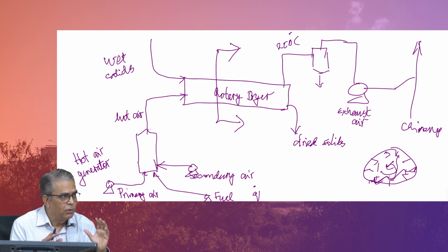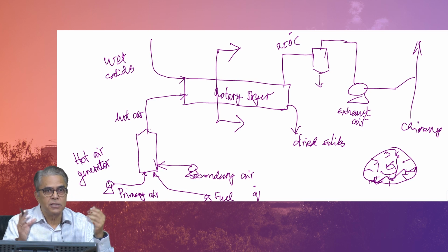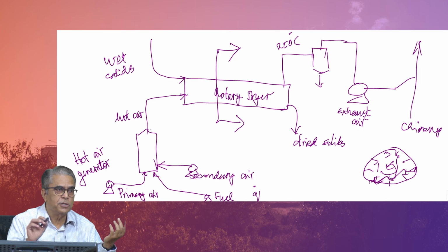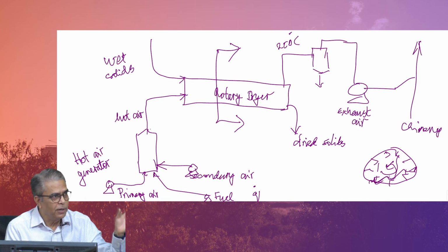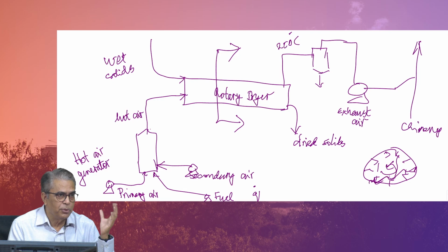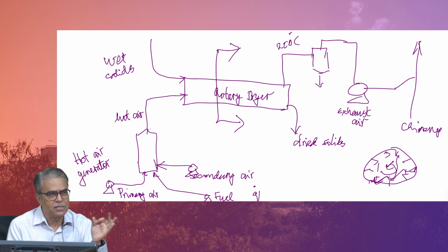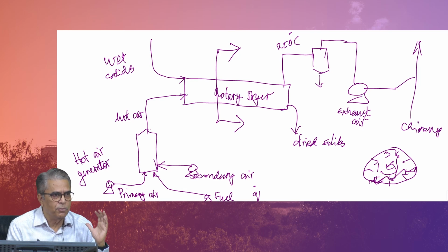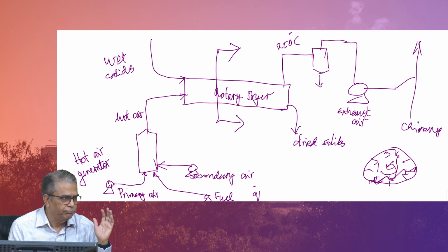Energy balance. Fuel, when it is completely burnt, releases the heat of combustion, and that heat of combustion will go to raise the temperature of the flue gas from temperature A to temperature B. So, we will do a heat balance calculation and find that temperature. In industrial jargon, it is called flame temperature. You burn the fuel in stoichiometric quantity or slightly in excess of that air. The maximum temperature you will reach of the combustion products is the flame temperature. Usually for gases, this flame temperature is very high, in excess of 1000 Celsius, 1600, 1700 for example.